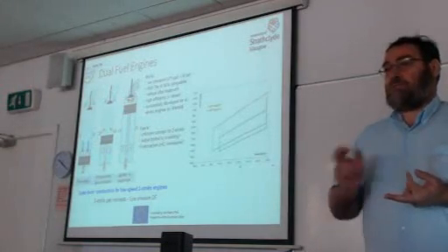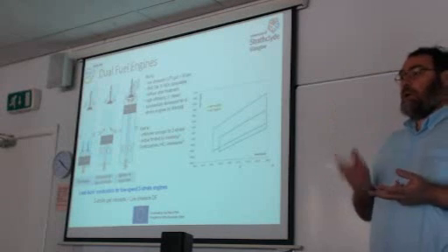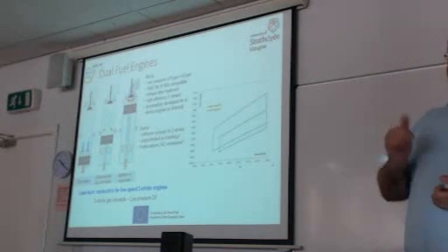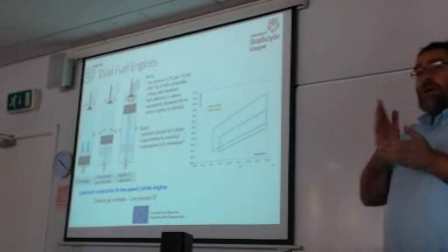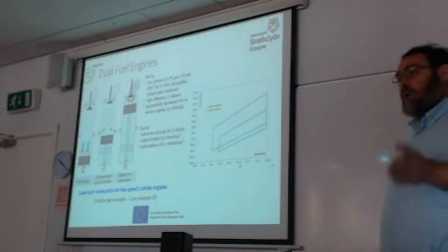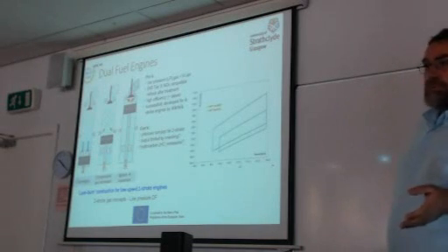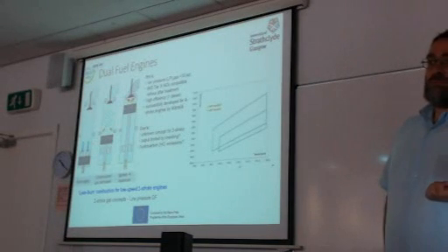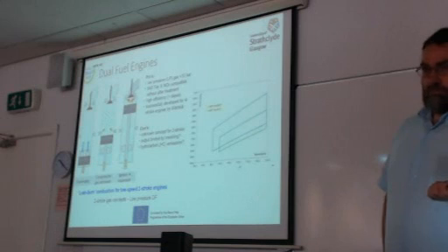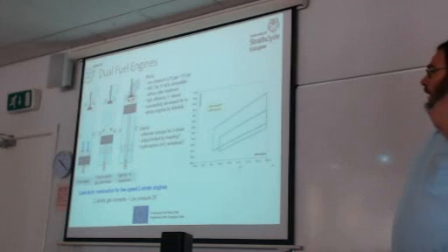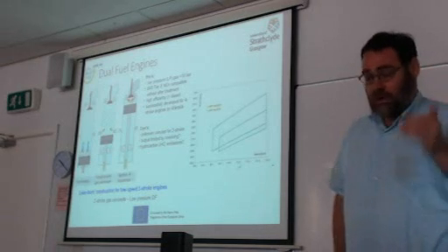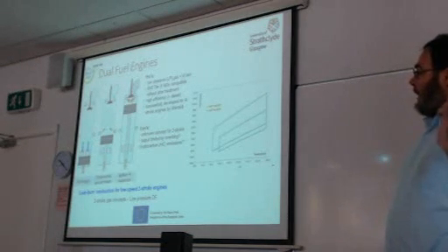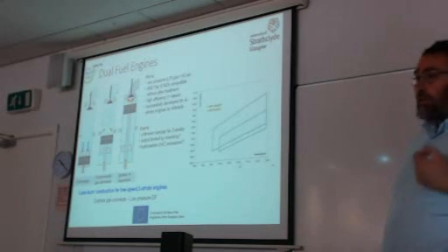As I mentioned, we have 4-stroke engines and 2-stroke engines. 2-stroke engines are used as prime movers, and 4-stroke engines are used as diesel generators, but also in ferry type ships, in cruise ships, or in small merchant ships. 4-stroke engines can be used as prime movers as well. So in which type of engines can dual fuel premixed combustion be used? 2-stroke or 4-stroke? For premixed, 4-stroke. In both. Actually, in both, as I will explain.